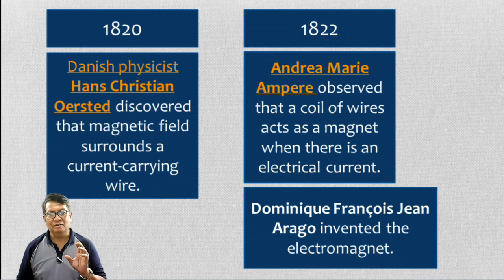But when it comes to electromagnets, you will be able to vary the magnetic field, the magnitude, or what we call the density of the magnetic field, by changing the number of turns or changing the amount of current that flows in that coil of wire.